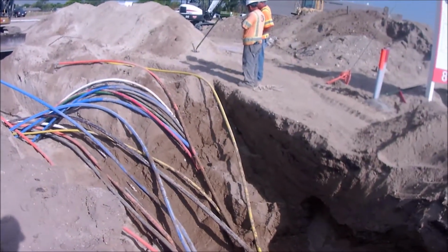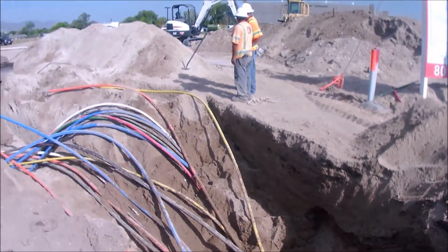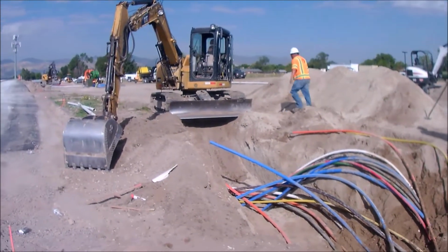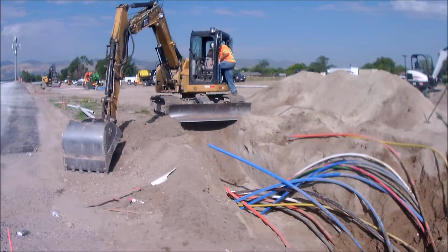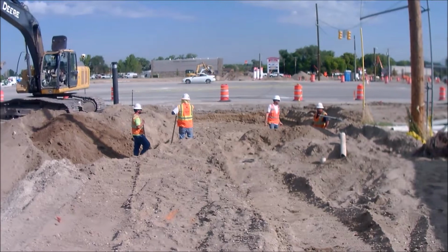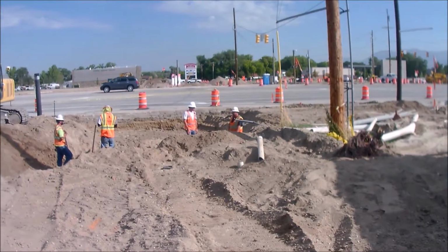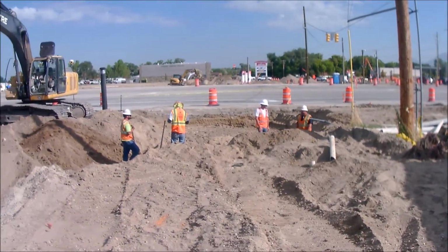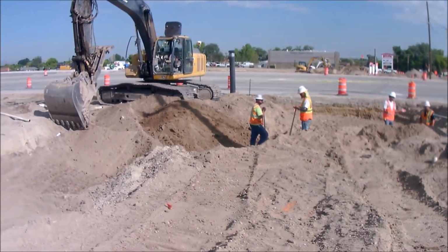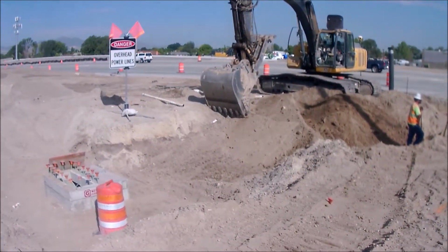Excavations and trenches deeper than 5 feet require sloping, shoring, or a trench box, and a trench excavation permit. Excavations deeper than 4 feet require a secure ladder or other means of egress within 25 feet of each worker. All project soil is presumed to be type C, requiring a 1.5 to 1 slope. Our insurance requires us to hand dig within 5 feet of buried lines. Trench boxes or shoring required for excavations greater than 20 feet deep needs to be engineered. Spoils piles will be located 2 feet back from the edge of the excavation.